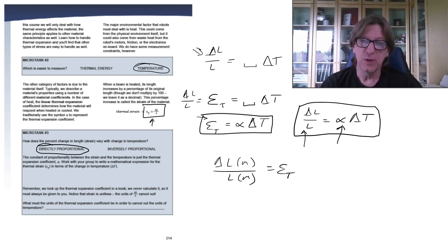Delta T has what units? Well, it depends on what particular unit system we're using, but we need to use Kelvin because our alpha will be expressed in Kelvin. So just like we talked about last time, we really need to make sure that we're doing all of this in degrees Kelvin. You do remember, though, of course, that my change in Kelvin must equal my change in centigrade in this case. Do it all in Kelvin, then you won't have to worry about it.